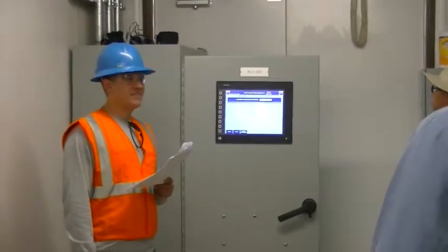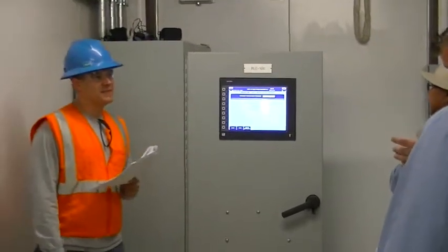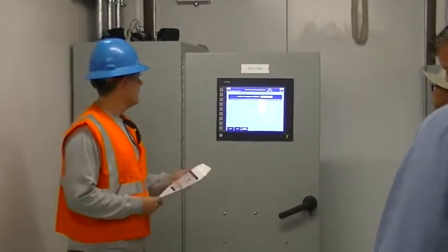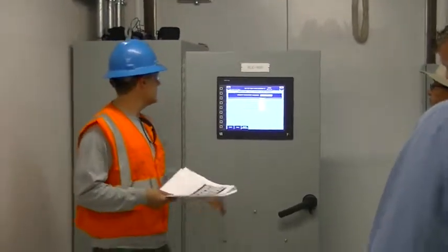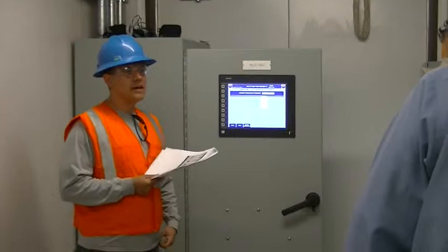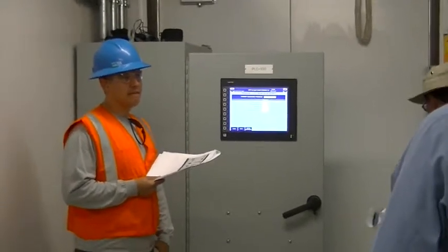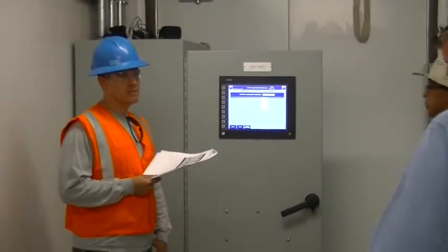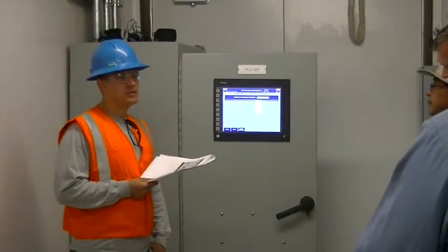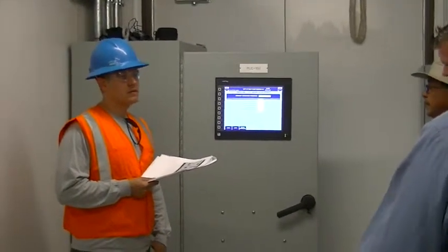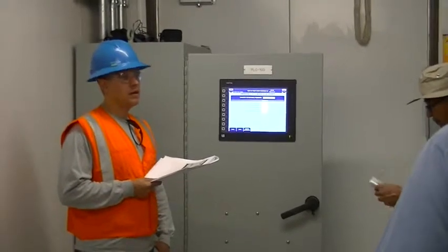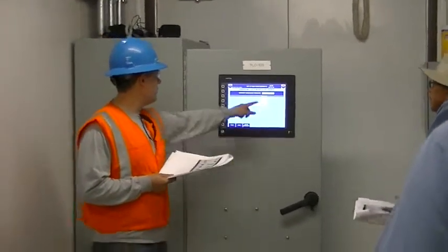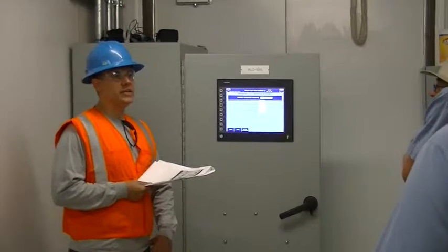Okay, so what did you call those pumps? I call them the RVSs. They're soft start. They're the big pumps, those are the 100 horse emergency duty pumps, right? Yes. Okay, so normally it would run off of the 60 horse, the smaller ones. How big are the small ones? They're 60. Correct. So normally it's going to run off of the smaller ones, and if they can't keep up with it, if it drops below that 50 PSI, that's when the big ones are going to come on.